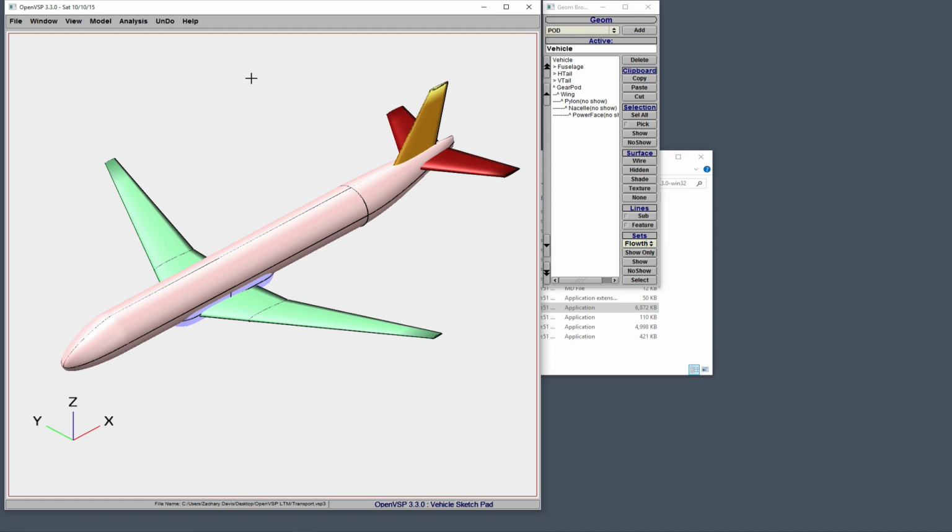A couple of features that were recently added to OpenVSP were the ability to create blunt trailing edges, on the trailing edges of wings for example, as well as the ability to export an analytical or mathematical representation of the parametric model using collections of B-spline surfaces to a standard CAD file format referred to as a STEP file.